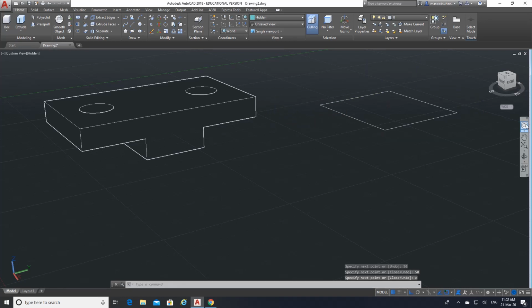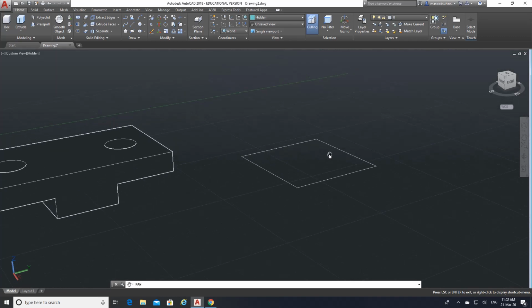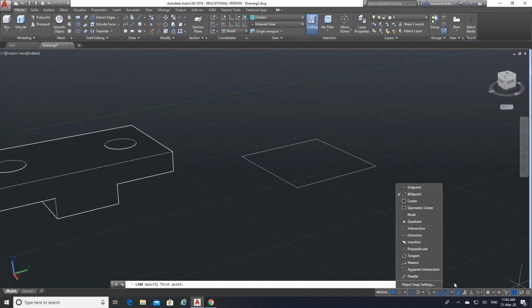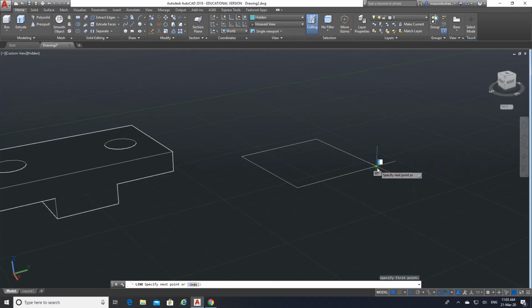So I have a rectangle now, I mean square now, which is 50, 50 each. What I will do is, I will just draw one line here from this. Let me remove the midpoint. I don't need midpoint. I will simply say intersection. Let me get rid of this. I will draw from here to here. Enter. So I have got a line over here.